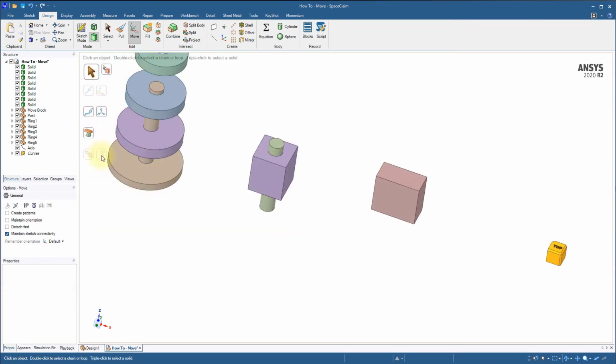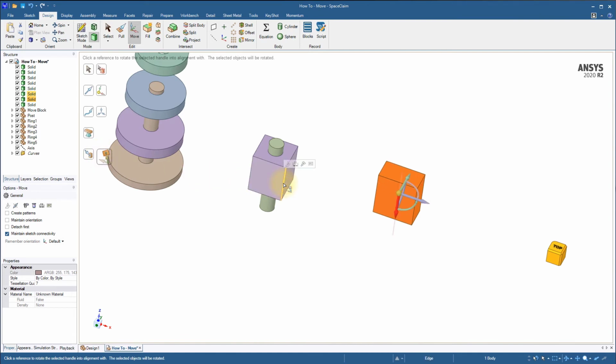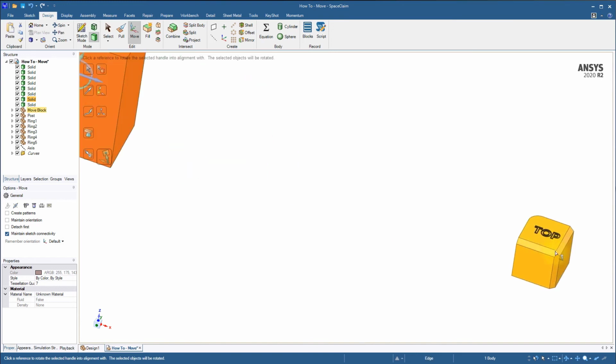Orient Object allows us to rotate the model to match the orientation of a selected object. The selected reference objects will then be parallel, but they are not required to be in contact. However, this option only becomes active under one condition. To activate Orient to Object, we must select only one of the translation handles on the Move tool. Before doing this, the operation is unavailable, because it would be impossible to match the three active directions on the Move tool to a single reference item selection.